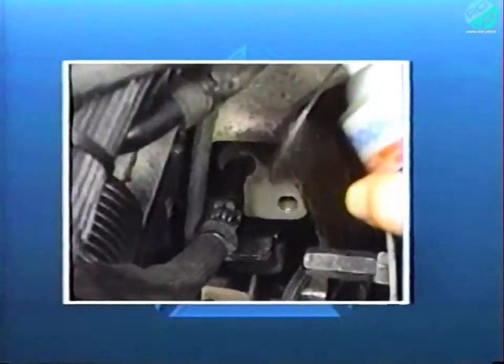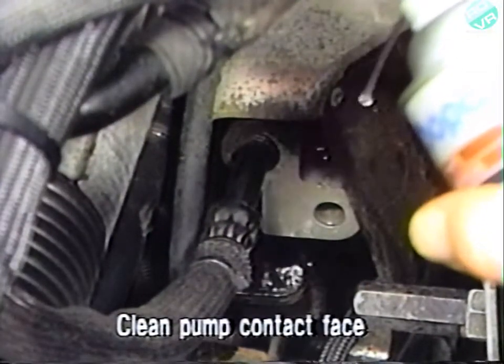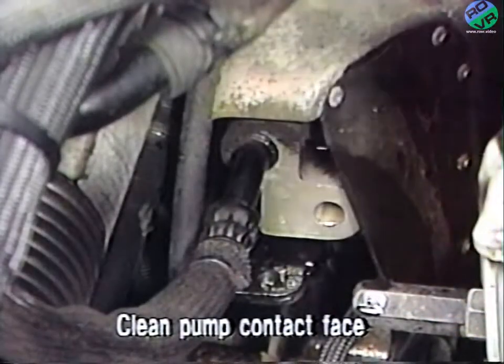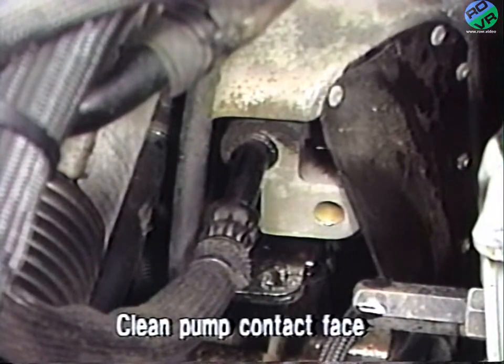When working with brake system components, be careful to prevent brake fluid from contacting any painted surfaces. If contact occurs, flush the area thoroughly with water. After removing the hose, clean the pump contact face for the high-pressure hose with Mopar brake parts cleaner or an equivalent.